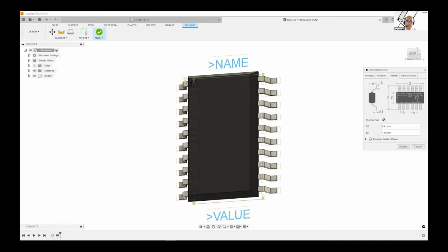Going further though, if you have components that are relatively large, let's say they're 10 by 10 millimeters, but have high density pin counts, with the thermal pad, you don't want all of that pad covered in solder paste.